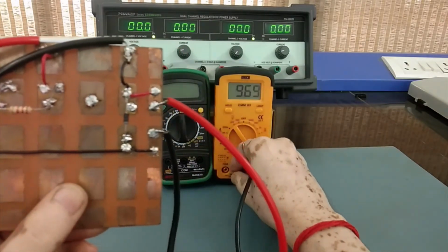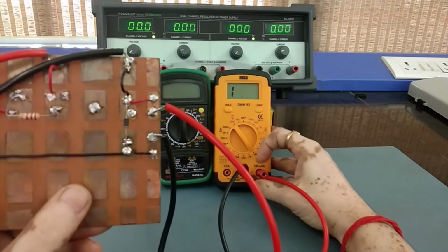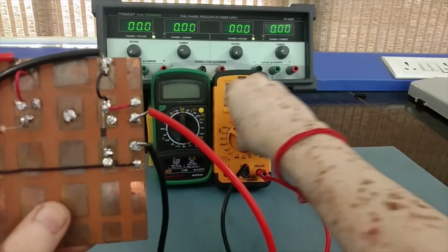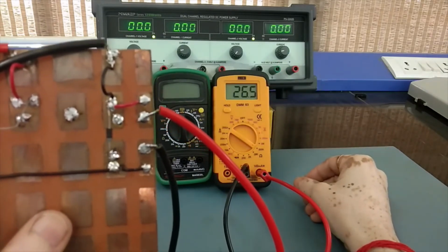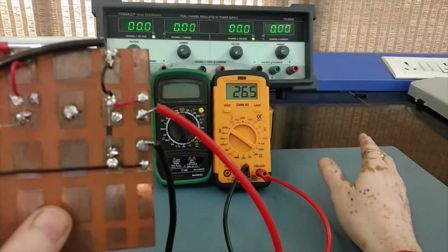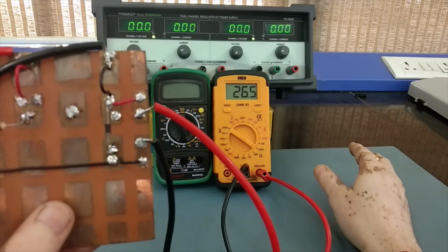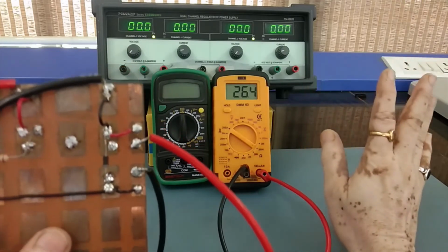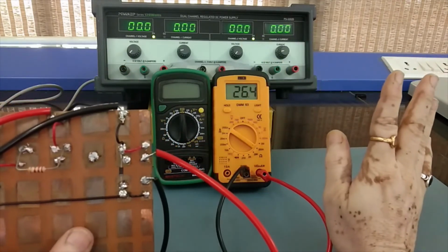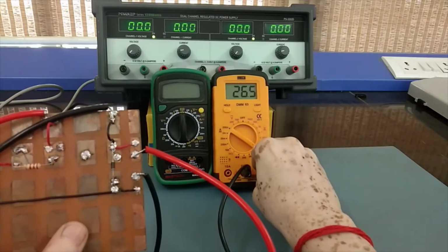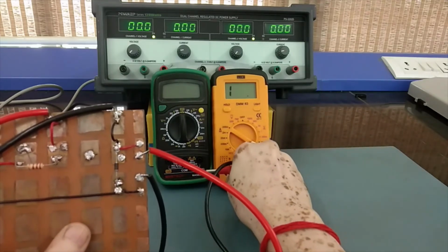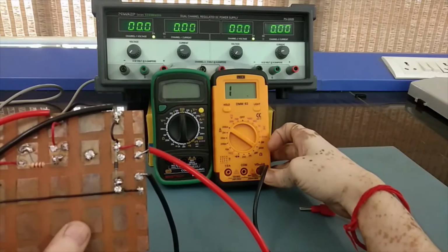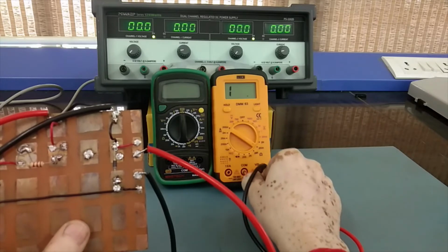We have connected it here. And you can very easily see that, okay, I will be increasing. So you can see in forward bias, there is 26.5 K, this much resistance. Okay, there is no particular value, but there is a finite value of resistance that you can measure. Now I will simply go for reverse measurement. Now I will be connecting the resistance of the diode in reverse bias condition.